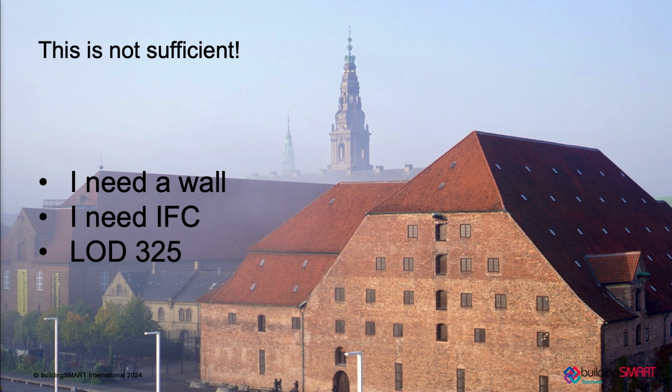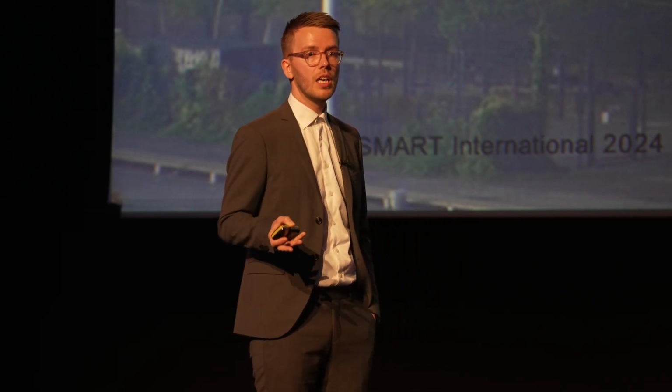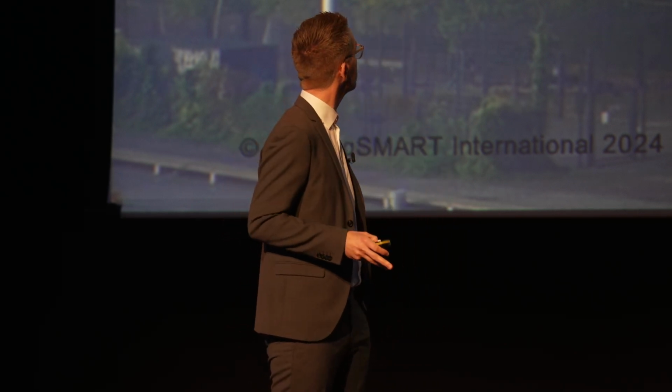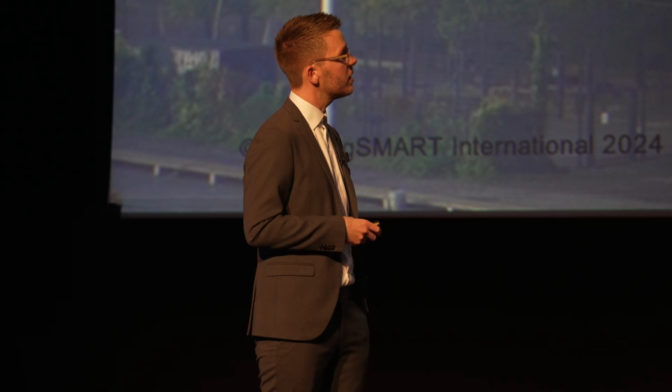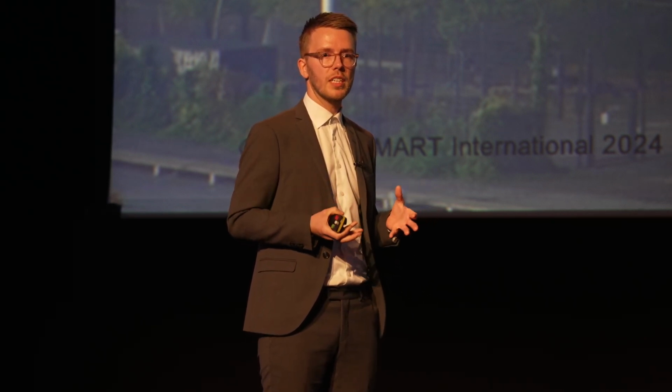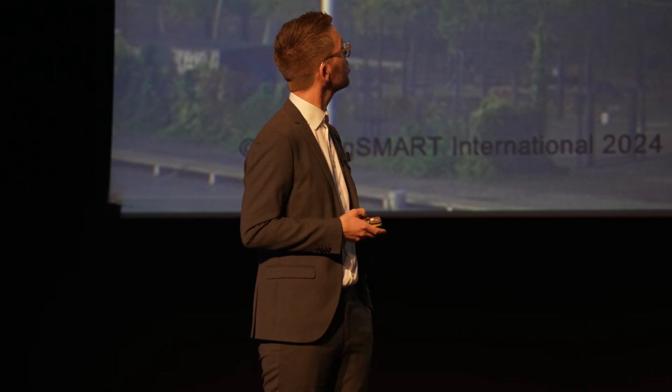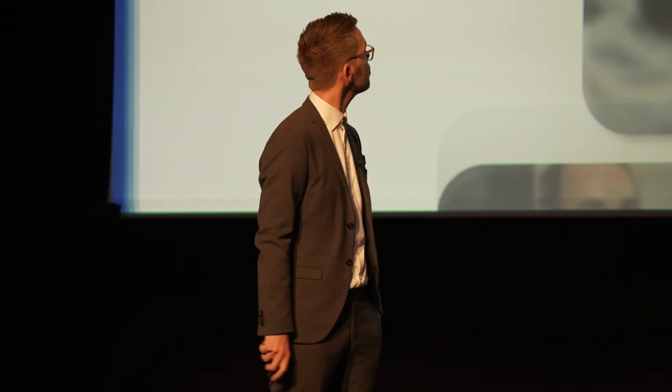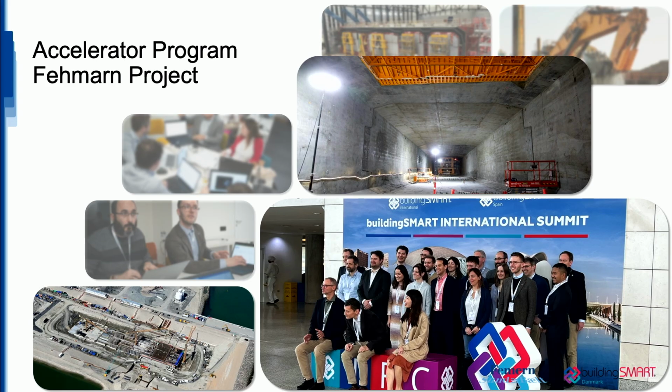So when we are talking about IDS, these terms are not sufficient. As I mentioned before, we can't just say that we need IFC. We have to be precise on which version of IFC is necessary. On this project, we have to be more detailed, as I mentioned before. You have to name the properties and property sets, and of course, the values if that's necessary. So now we're going to talk a bit about some examples from the Fehmarn project, where Giulia will start, actually.